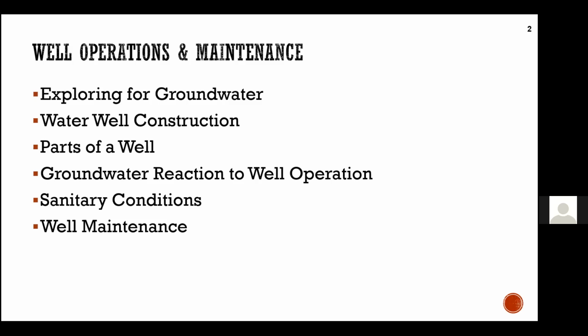Because remember, when we were looking at surface water and impoundment of reservoirs, lakes, and then man-made reservoirs, we have to disinfect because that water is basically open to contamination by animals, by birds, aquatic life, and people if we use those reservoirs for recreational purposes. With groundwater, we have an advantage in the sense that the actual water itself is often, not always, but often safe from bacteriological, biological contamination. So in many utilities, there's no disinfection when water is taken out of the ground.